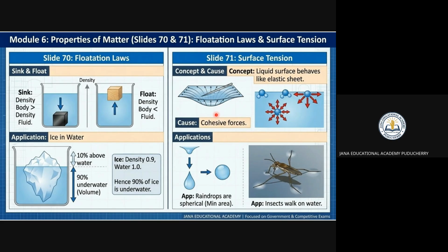The one thing you have to remember in floating and laws is the weight of the body and the buoyant force, right? The weight of the body and the buoyant force. A body floats in a liquid when the weight of the body is equal to the weight of the liquid displaced by it, right? That is nothing but the buoyant force. The body is going to displace an equal weight of the liquid. So if it is 1 kg, 1 kg equivalent of water is going to be displaced. That is nothing but the buoyancy law. You will see it in the next slide.